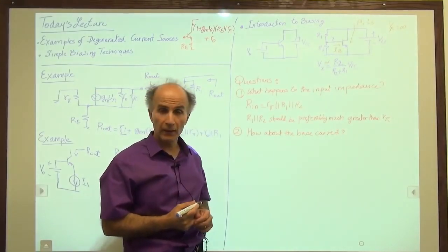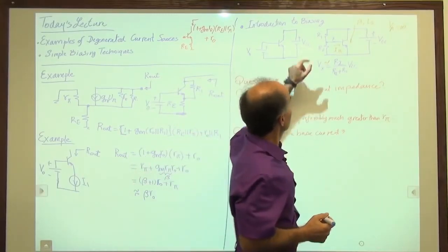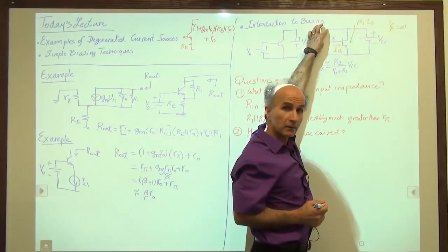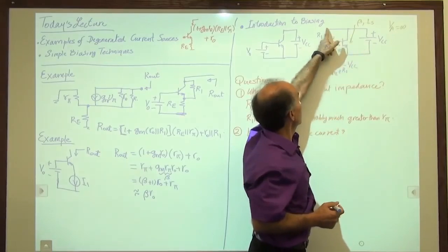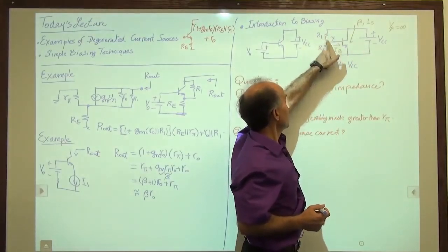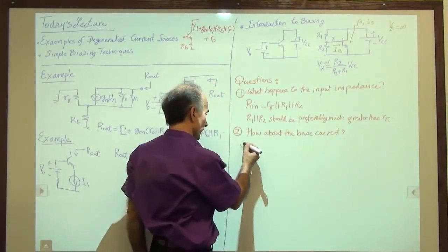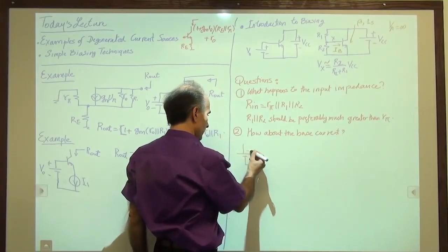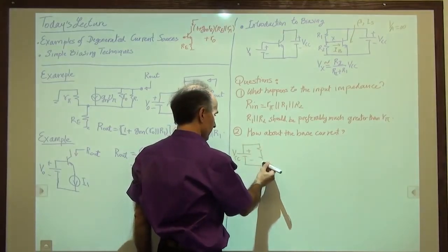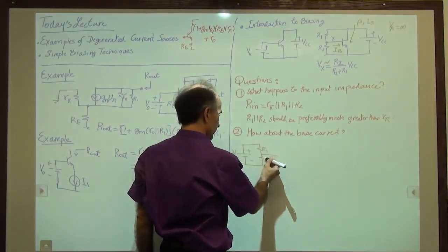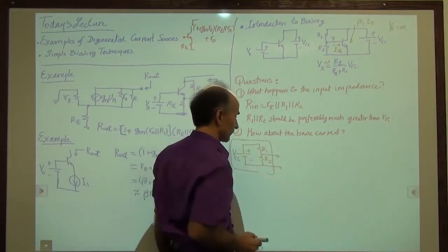Well, I will play a little trick here to simplify the calculation a little. And that's based on recognizing that this voltage comes from a battery, this battery here. So I can take this voltage source that goes to these 2 points, and this resistor, and construct a Thevenin equivalent for them. So here's what we have. We have a battery, VCC, and then 2 resistors, R1 and R2, and put this in a box and construct a Thevenin equivalent for it.